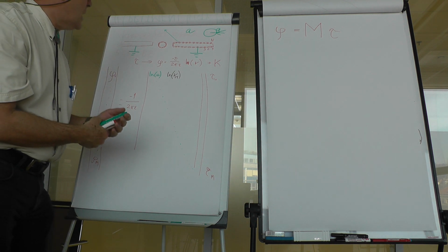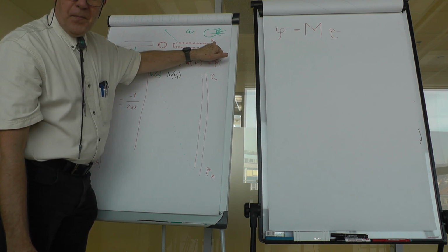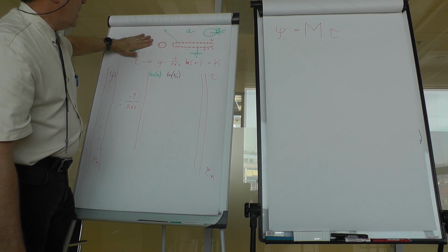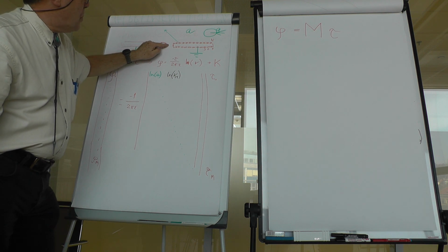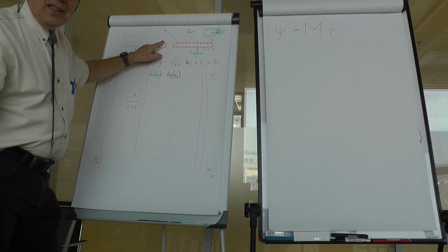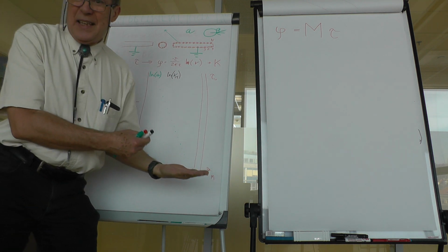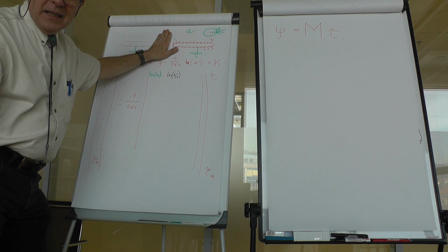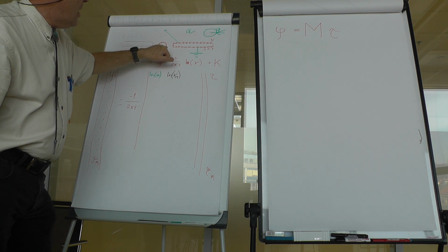So if I would like to calculate the capacity, I would put, for example, here the potential of 0, and of course on the other one 0 voltage part. Then I would assert a potential of 1 on the other conductor, I would establish the electromagnetic field, or electrostatic in this case, and once obtaining that, we can find out the charge just by adding the charges on this conductor.